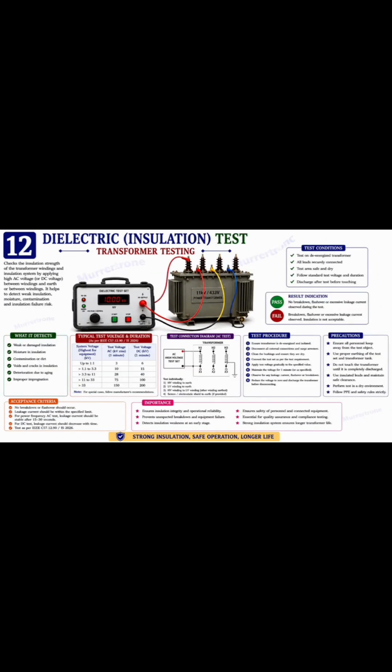12. Dielectric insulation test. This test checks insulation quality of transformer. Types of dielectric tests are induced voltage test, applied voltage test, lightning impulse test, and partial discharge test. Its purpose is to verify insulation integrity, to simulate overvoltage conditions, and to ensure long-term reliability. Importance. Mandatory during transformer manufacturing and FAT.